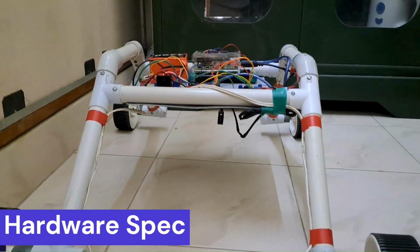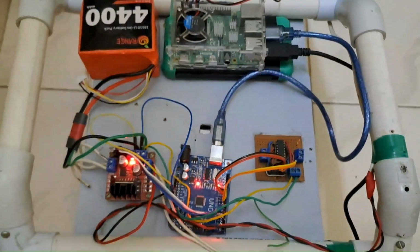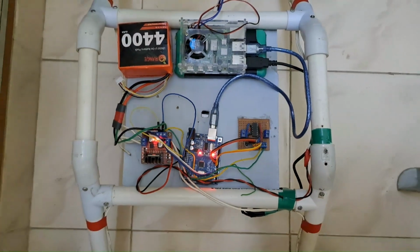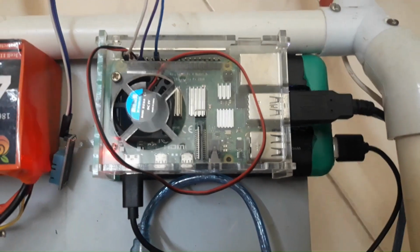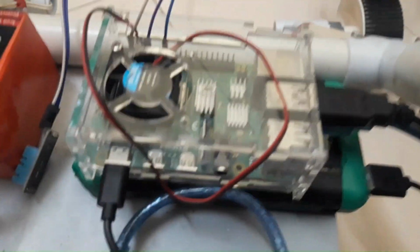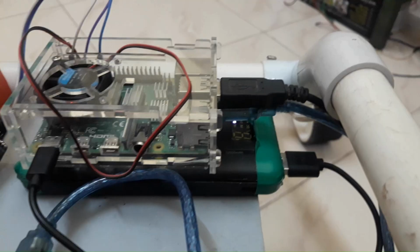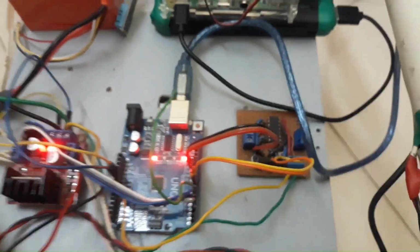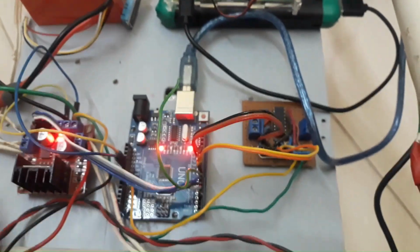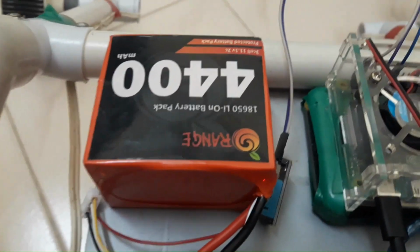Now let us see the overall hardware specification of the robot. The robot uses the Raspberry Pi as the brain of the computer. Here we use the Raspberry Pi 4 Model B with 8GB RAM. Further, an Arduino UNO is connected in serial communication with the Raspberry Pi. The Arduino UNO is mainly used to drive the 4 wheels, and a motor driver is used to control the 4 wheels. And a lithium-ion battery of 4400 mAh is used to supply the power to the robot.